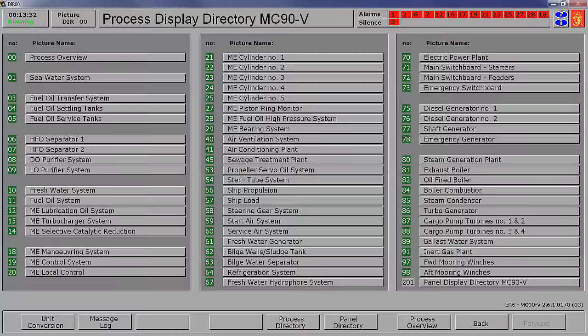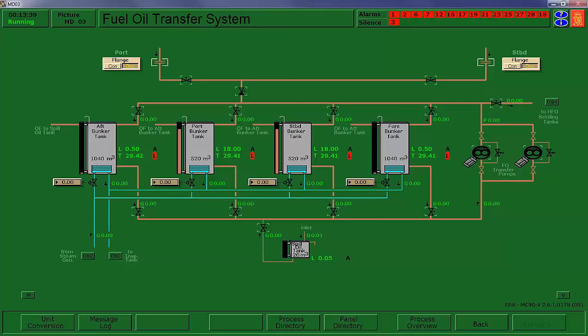So as that boiler starts producing steam, it's going to start going out there and do its heating. We've got these 2 bunker tanks that we need to heat up. We're going to open up the supply to them at 100% right now. They're only at about 30 degrees C, so we cannot pump oil. This is too cold to even pump it. We could not transfer pump oil right now, so we need to start heating that.